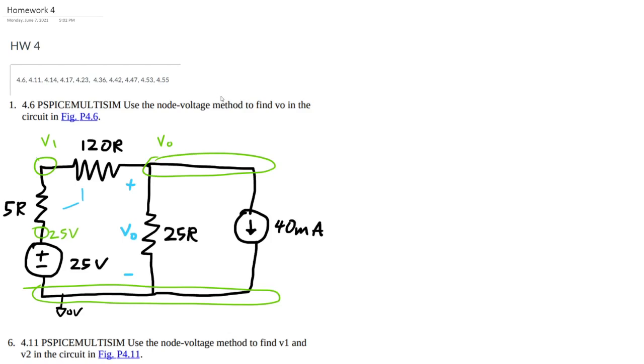Anyway, in nodal analysis, you consider each node that you're analyzing as if all the currents are leaving that node. It may not be the case, in which case you'll have a flipped sign in the final answer, but it's okay. Just assume all of them are leaving. So we'll do a KCL at VO and assume all of the currents are leaving.